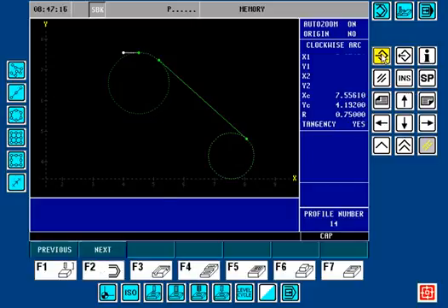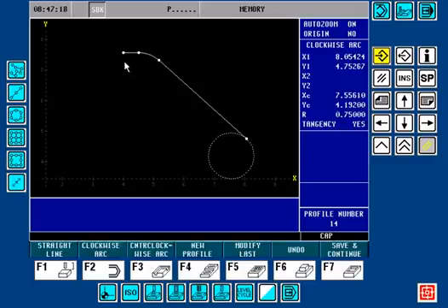We're going to go ahead and press Enter to save it. Now you'll notice that the white dotted line was automatically trimmed to the tangent line coming off of the arc. Now we have our line completed, but we have an incomplete circle here.